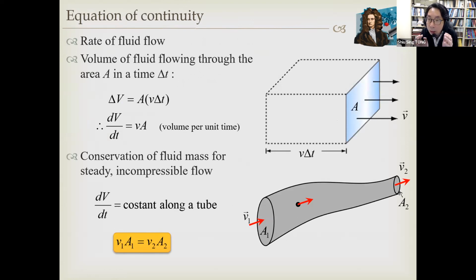In the so-called ideal fluid flow, we assume an important thing: that the density of the liquid doesn't change. We assume that the liquid is incompressible, because you need a very large pressure to compress the liquid by just a little bit. So for most of the situations that we are dealing with, we can assume that the liquid, and even the gas, may be almost incompressible.